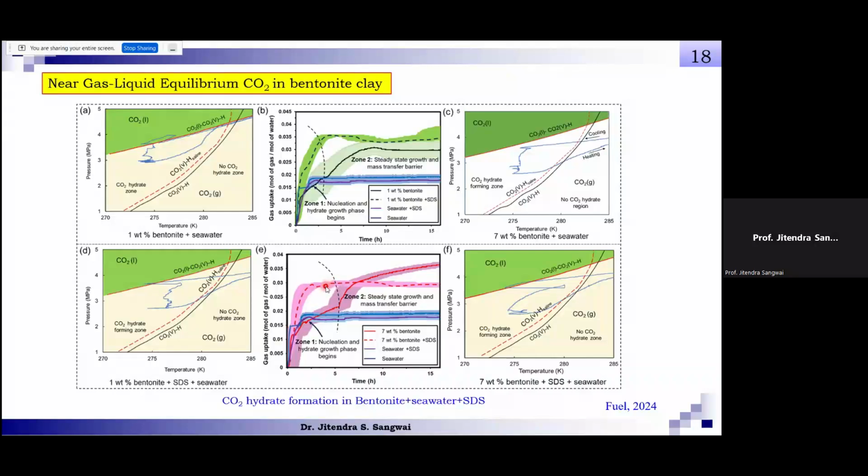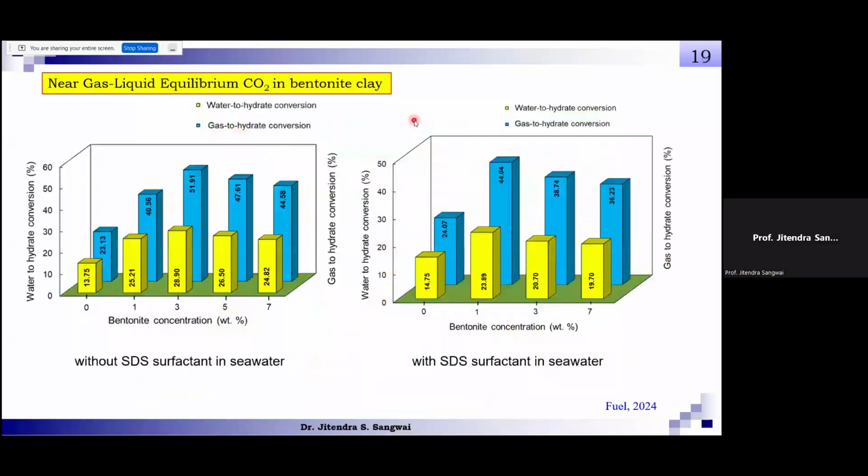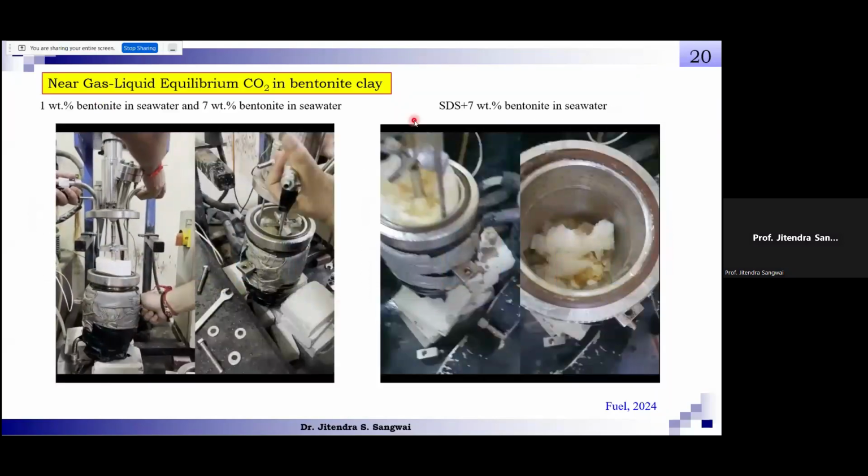When you use some kind of surfactants, right? Some of these studies are being done using various methods at the lab condition, and it has been found that when you look at the effect of surfactants, or some of these promoters, they may provide some additional advantage. Sometimes surfactants may not necessarily provide advantage because you may end up having a foam rather than surfactant helping you out. Right, so you have to optimize the concentration of some of these promoters to ensure that you have favorable hydrate formation.